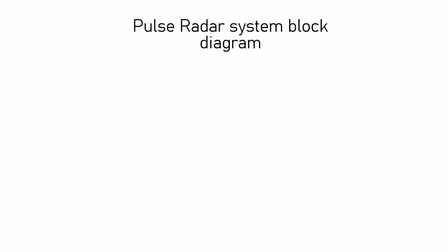This shows the block diagram for a pulse radar. The transmitter is a high-power generator of pulses of microwave energy. For example, a typical airfield radar, like an airport surveillance radar, ASR, usually operates with a peak power in the range of several hundred kilowatts and a pulse width around 1 microsecond. However, specific values can vary depending on the radar model and desired performance characteristics like detection range and resolution. The microwave frequency depends on the radar application, but an airport radar will operate at between 2.7 and 2.9 GHz.